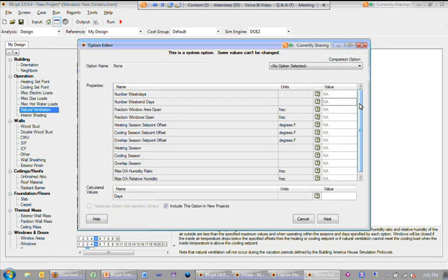And I did want to reiterate what Eric said. This would be a classic case, among others, where if you are doing the inputs for ventilation, cooling, for example, anything with controls, it's definitely a good idea to open the hourly results in DView and inspect what's happening to see if the building is performing as you intended. And that's not a bad idea just in general, to look at hourly results.